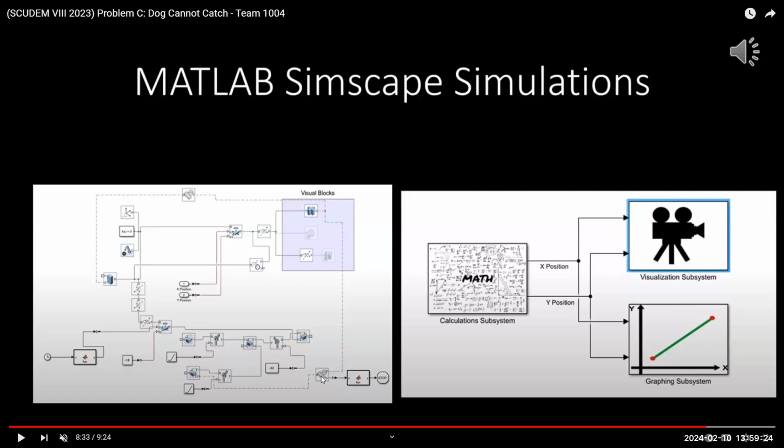This also means, though, if someone else gives me a SolidWorks file and says, can you make a Simscape model out of this, and they constrained things so that two pieces are always 5 meters apart, it'll become very difficult for me to change that if that's not how the part's supposed to behave. So it really does depend how long it takes me to make the model on how somebody assembled the whole thing. For this model, it didn't take me a lot of time because I made the dog completely rigid and I gave it the motion that I wanted in Simscape. That way, it doesn't throw in joints that are not needed.